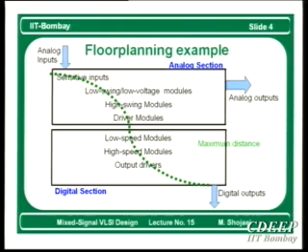Second, these signals, if we are talking about CMOS technology, are applied to a high impedance input. Therefore, analog inputs are applied to high impedance inputs. See, double effect. You have a high impedance node which can pick up noise, and you have a low amplitude signal which is entering the circuit. Therefore, you have a double problem.